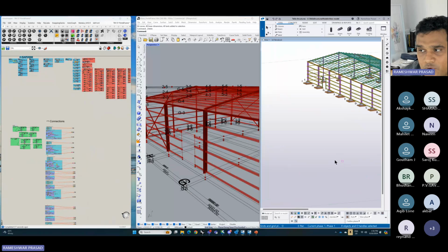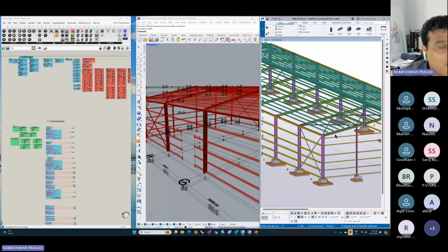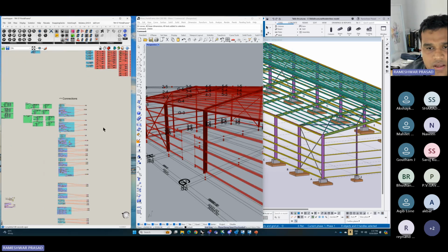And you need to provide a few extra details as well sometimes for a few connections, because what happens is, when you're modeling a connection in Tekla, based on the location of the plane, the camera, and the mouse, it kind of judges certain parameters by itself and assigns those parameters in the packet. The local X plus, Y plus, and those things, if you have ever modeled a connection in Tekla, cannot be transferred from Grasshopper. So sometimes it models the connection in a reverse fashion. That's why you have to feed those values additionally to the connections.